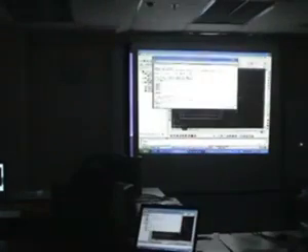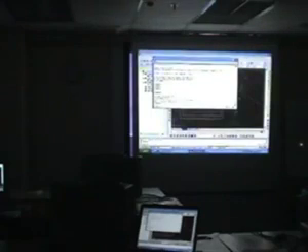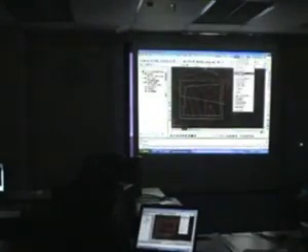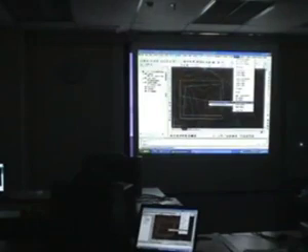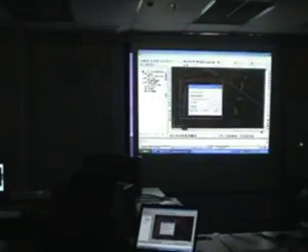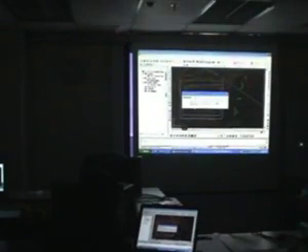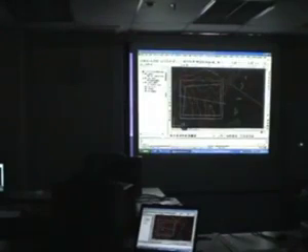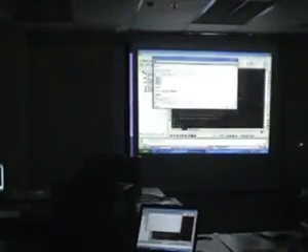So I'm going to open up the history to show you. This is our cut volume, our fill volume, and our net volume. This is for the platform. Yes, that's for the platform. For the second method, it's almost the same. You just pick calculate total site volume. Pick the site, and again, you can specify your fill factor. I'm going to put it the same as just now at 1.2. Okay, again, I'll call up the history. You can see our cut volume, our fill volume, and our net volume.